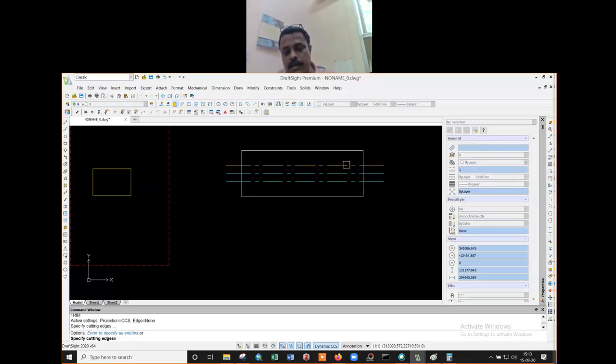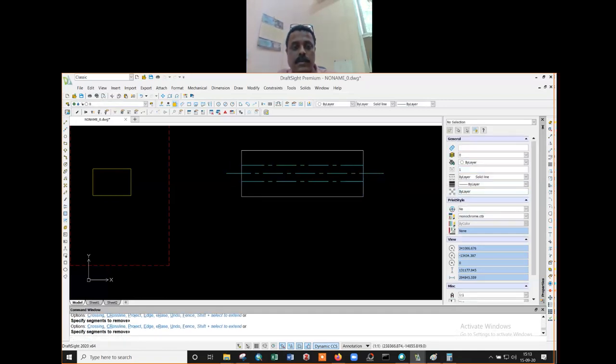Anyone? What kind of line or center line do you use? What kind of line should these two be? Remember, first of all you have to get a grasp of the drawing theory itself. Suppose this is a part of this object. Then I have a hole through this bottle, and you are viewing it from this side, because you cannot see the hole directly. If you want to represent the hole, what kind of line will you show?